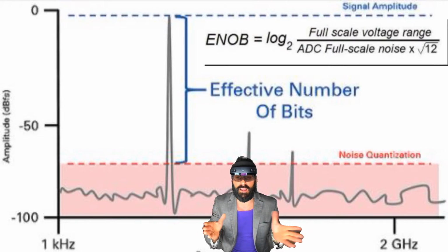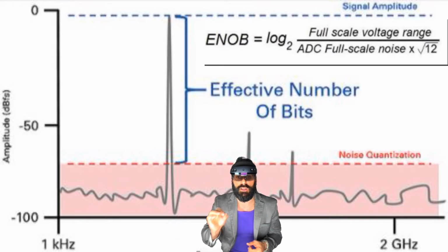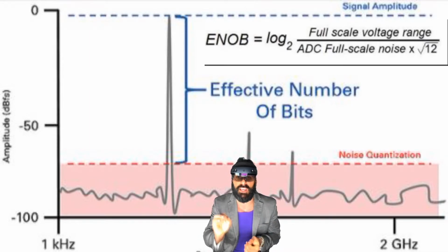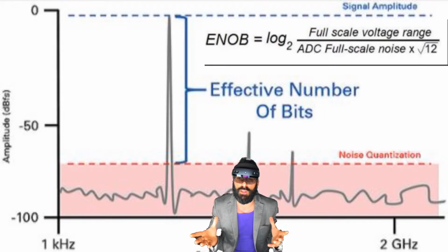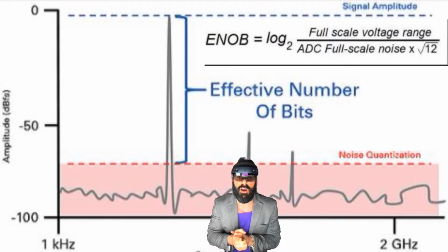It could be crosstalk. Some errors will even creep up from the effect of one channel through crosstalk on the PCB. So testing systems with an ENOB will provide a valid benchmark of the system capabilities and its accuracy. It's not a replacement for a signal-to-noise ratio and other error specifications provided by the manufacturer, but the ENOB test, when compared with all of the other types of input variables, can give you a very stable understanding of what the system is capable of in a noisy environment, specifically in power systems.